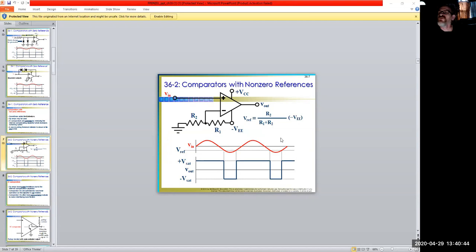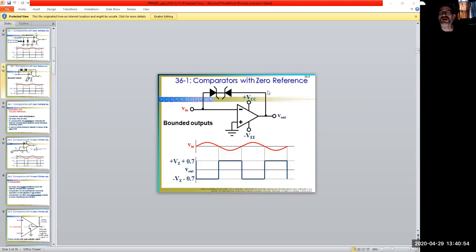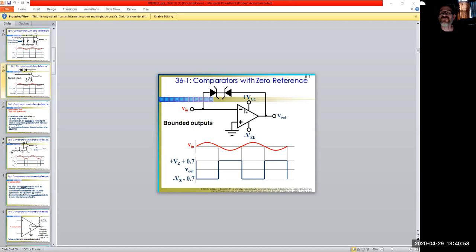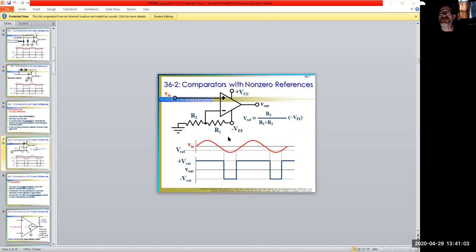So we're not reproducing a nice smooth analog signal. We don't have the feedback loop in this case. So these are all what they would call open loop functions. If you look at all the model types, this is an open loop. There's no feedback resistors. There's no input resistors to these.